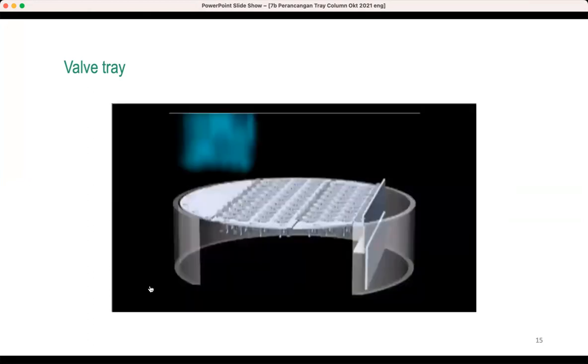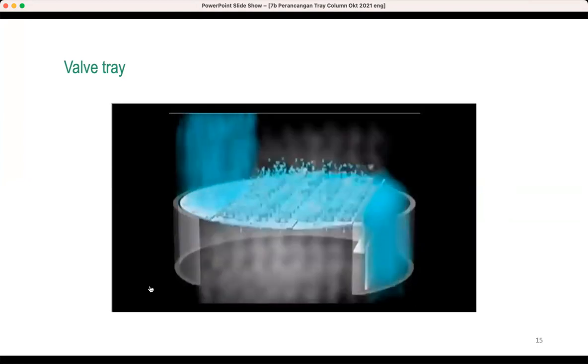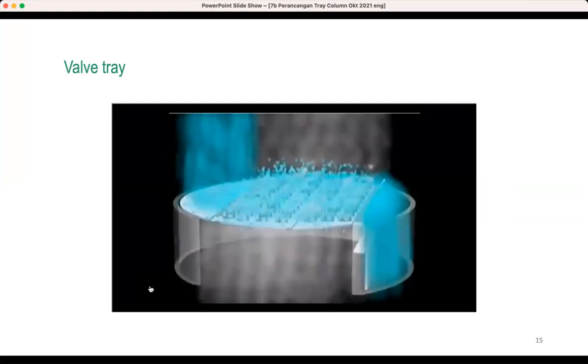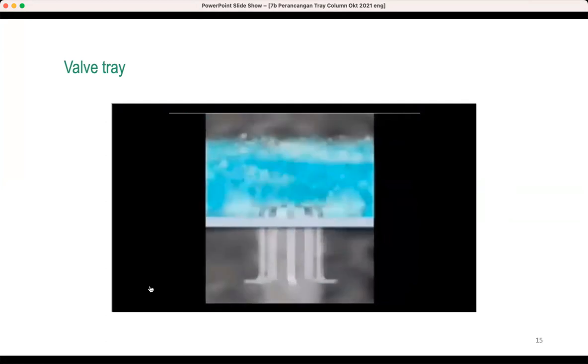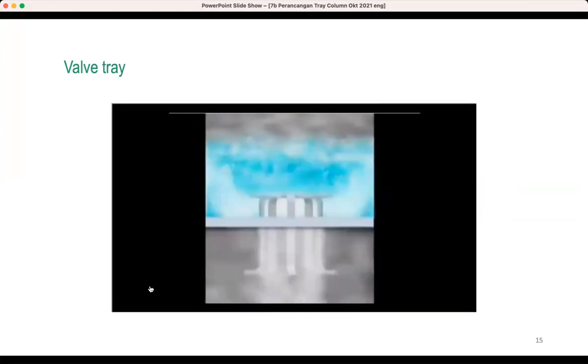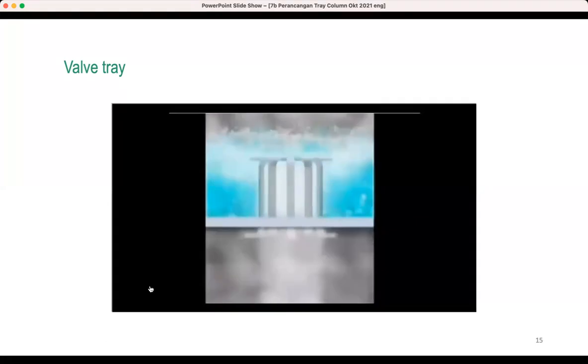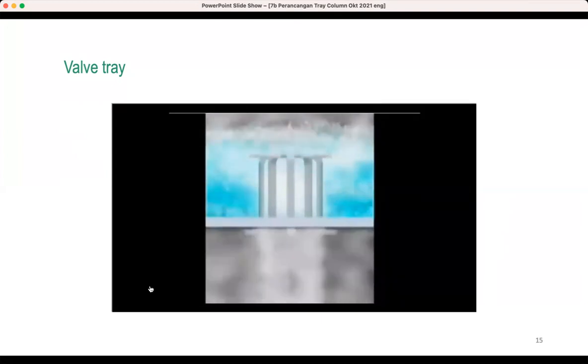Valve trays, along with sieve trays, have dominated for the last 40 years. Valve trays generally are proprietary and contain movable valve units. When the vapor rate is low, the valve partially closes and minimizes weeping by restricting the liquid flow through the tray holes. At high vapor rates, the valves deflect the vapor flow. This reduces entrainment by creating a weaker vapor jet and results in a greater operating range. The valves do contribute to vapor pressure drop, as the vapor must push the valve open.